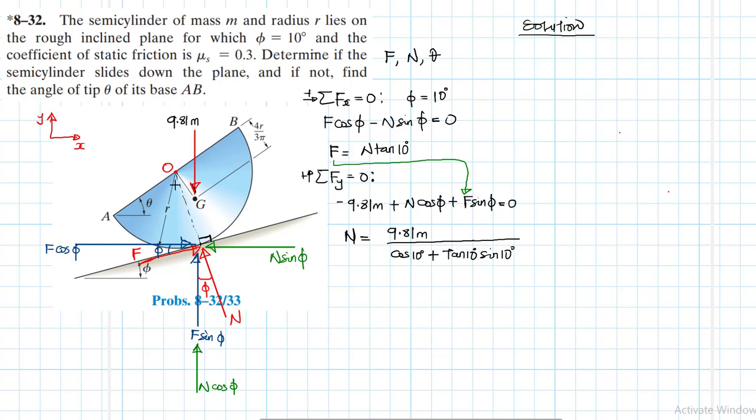So let's take another equation, about point O. Summation of moments about that point equal to 0, with clockwise being our reference. Before we take moments, I'll need to draw to indicate other components that are here. We know that this angle here is phi. Therefore, this one here is going to be theta, sorry.